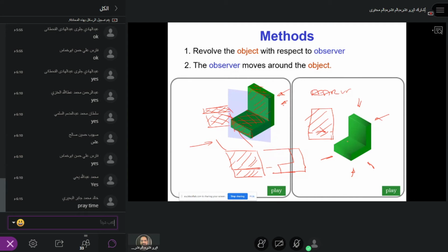But for most of the components, the front view and side view are used in order to check the width, length, and height. If you need the rear view, you can draw it. But will that be helpful? Nothing, because you cannot see this surface from the rear view. So unless otherwise necessary, you don't need to draw all the views. Understand? Okay.